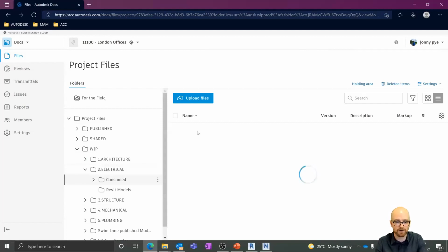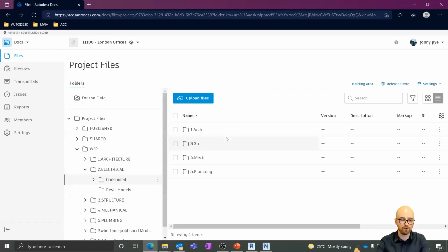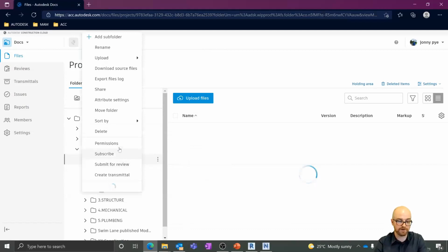And this is where all the links would be to your Revit model. I'm going to be going through this in Revit, so you'll see this process. But now I've updated that model. When I go into Revit, I could refresh, reload my models, and I will have that new architect's model. But you can see using the swim lanes, you have the opportunity to check the changes before you put it into your link.